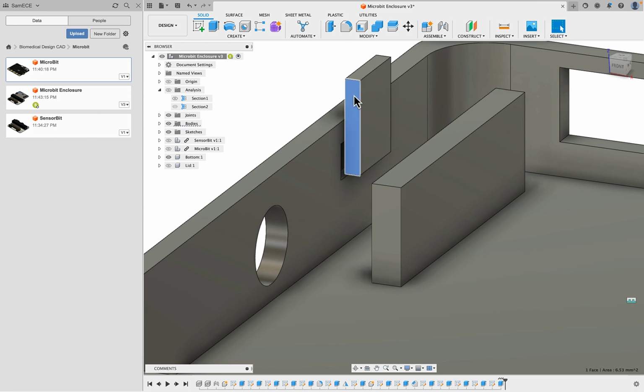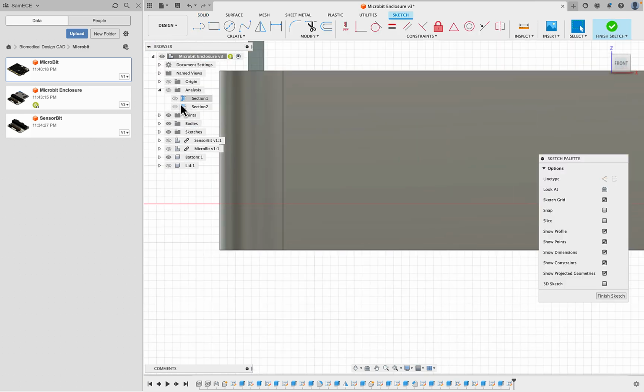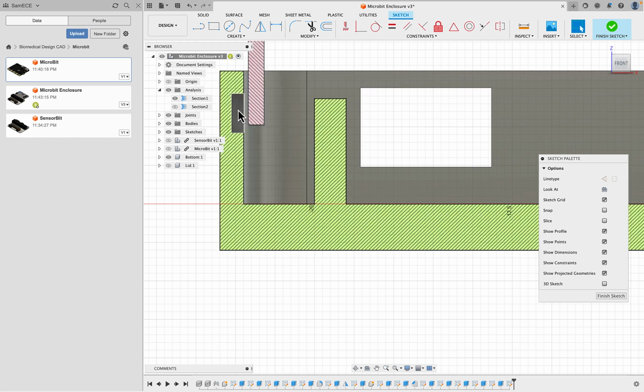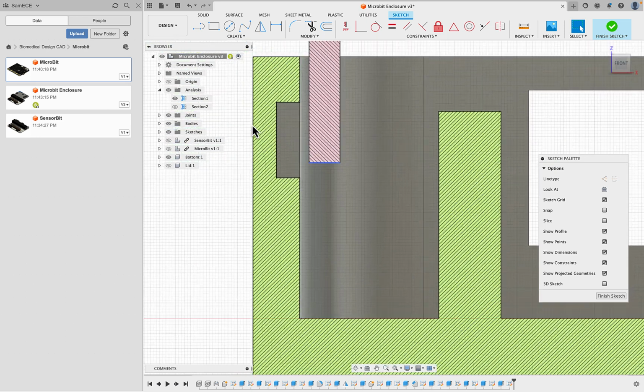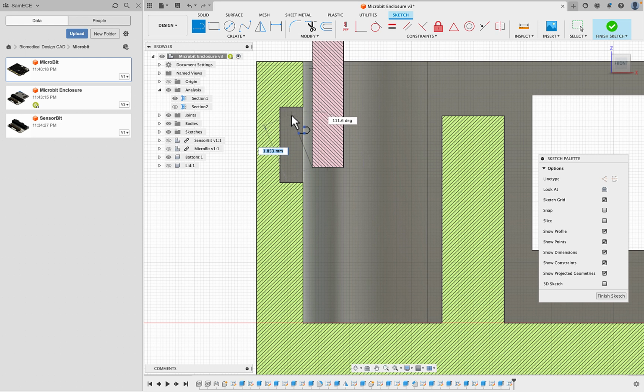So let's hit this surface here and do a sketch. Now I would actually like to see the section here. So now it just makes it easier to draw the right triangle. So hit an L and go from this corner somewhat into this one again. If I do too much, then it'll snap off. Let's just do this part here and do a distance from this point to that line, using 0.25 in this case, and a distance from here to here of, let's say, 0.3. Should be okay. I think I'll do this one just a little bit at 0.4.